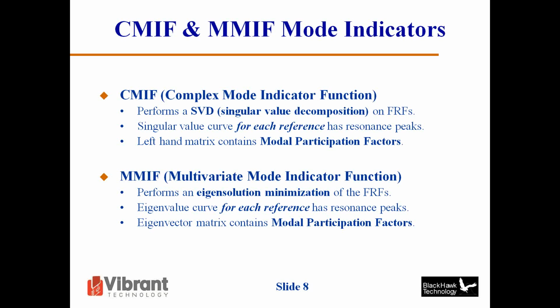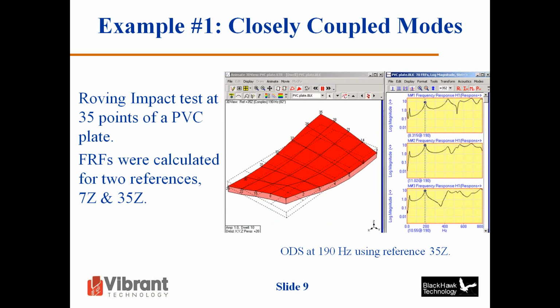You need all the curve fitters that you can get your hands on, and then our approach is that you compare answers from different approaches, and here we can compare answers from the CMIF and MMIF and get a better understanding of how these mode indicators operate on different kinds of data.